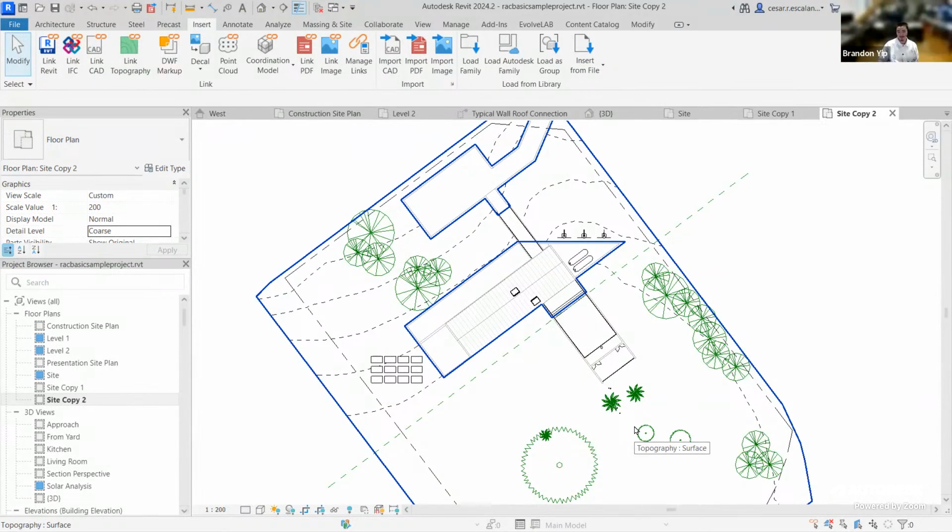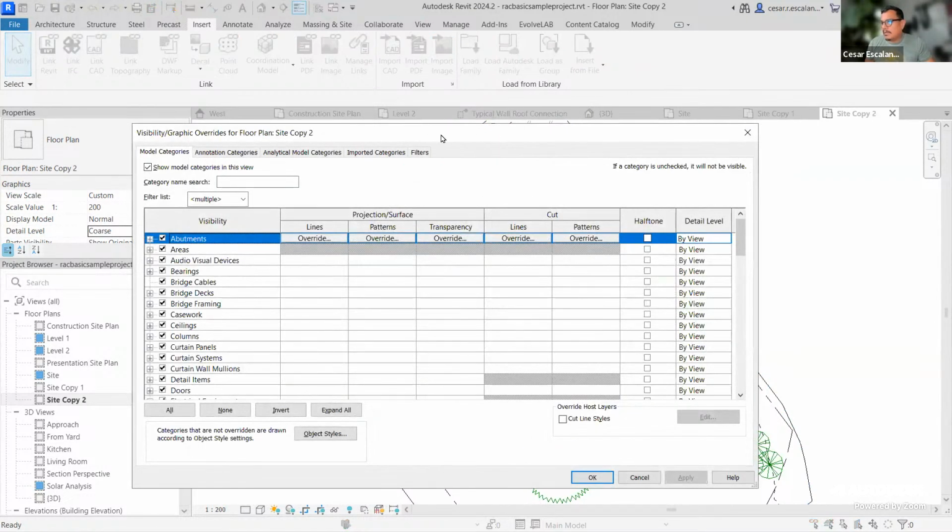And so inside Revit, inside Visibility Graphic, when you link something, there's a new tab that appears here called Revit Links. And that lets you access the VGs of the link file. So if you want everything half-tone, it's just a matter of selecting that link and enabling the half-tone properties in that remote visibility graphic setting.